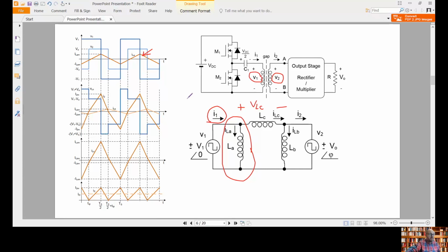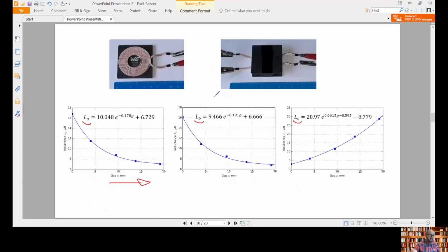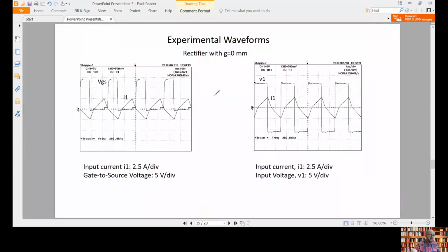This is a similar situation as in the LLC resonant converter, which is very popular because of this characteristic: we can obtain low switching losses when operating at low loads, because we always have some current circulating through the half bridge inverter. So this could be an advantage of the non-resonant circuit.